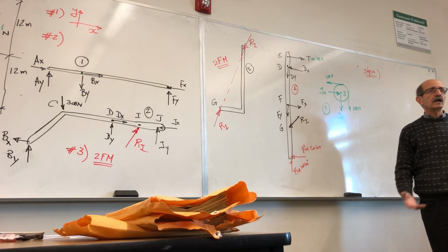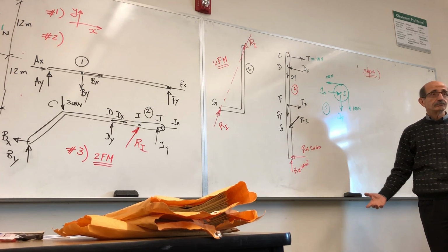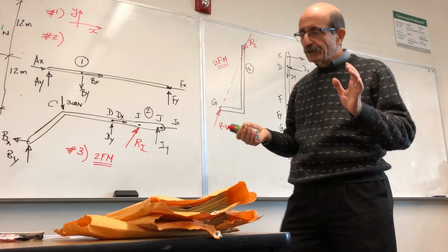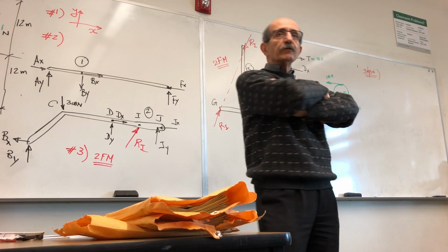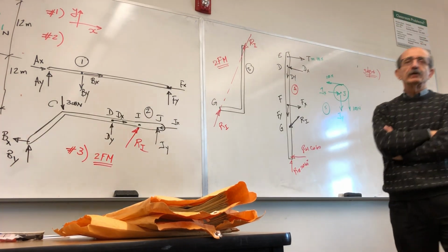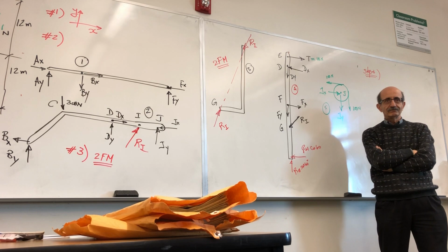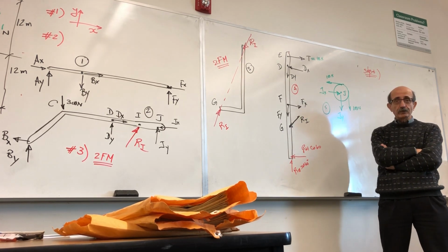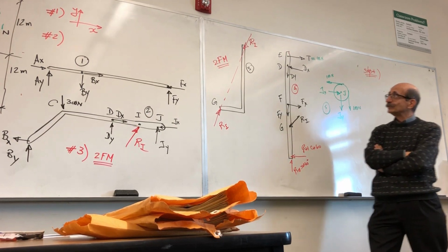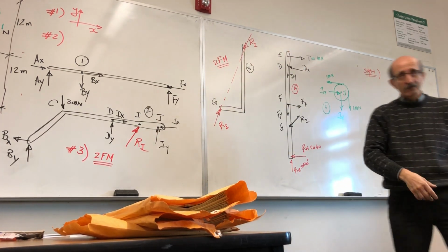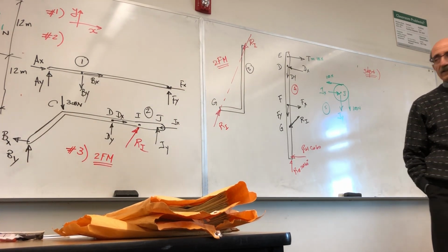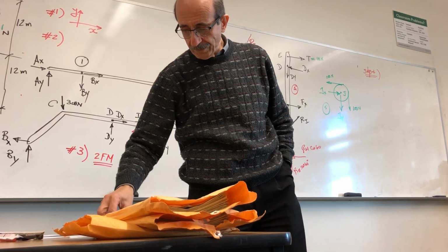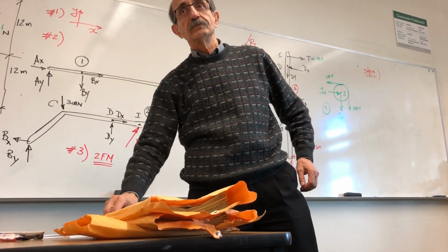So which free body diagram should I start with? You start with 3, but remember, anytime you have a two-force member, the free body diagram of that member you've already used. In fact, you already applied the equations of equilibrium to figure out that these two forces are equal in magnitude and opposite in direction. So because of that, remember that diagram for the two-force member is useless.